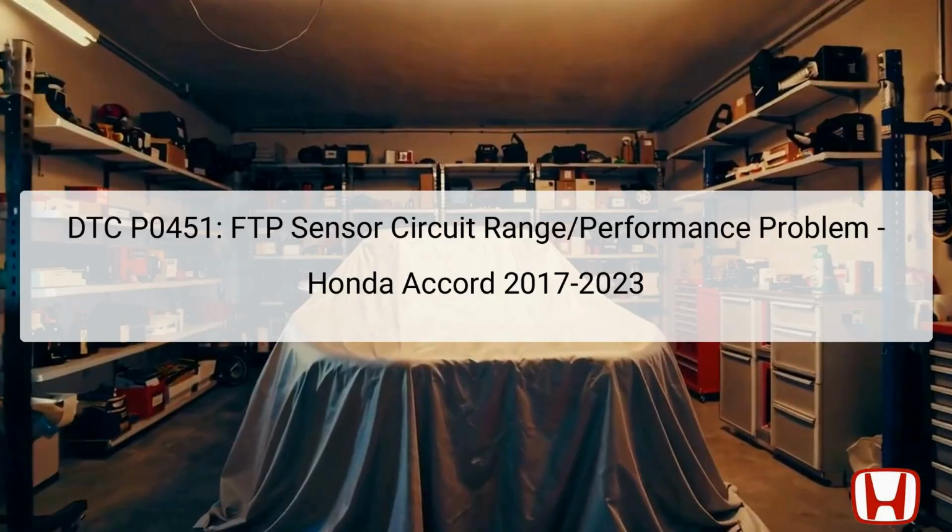The Diagnostic Trouble Code, DTC P0451, indicates a problem with the fuel tank pressure FTP sensor circuit related to range or performance. This sensor plays a crucial role in managing the fuel system pressure to ensure the proper operation of the evaporative emissions control system. Located near the fuel tank, the FTP sensor measures the pressure inside the tank and sends this information to the Powertrain Control Module, PCM.